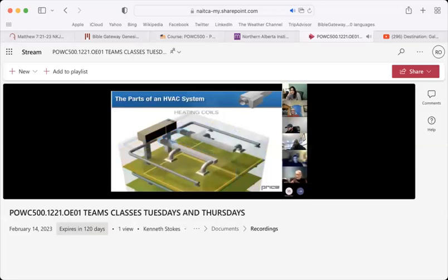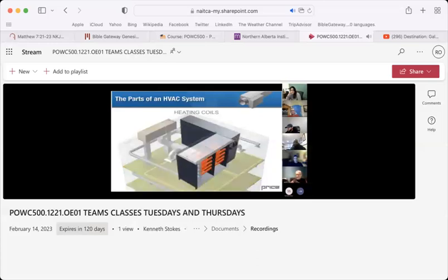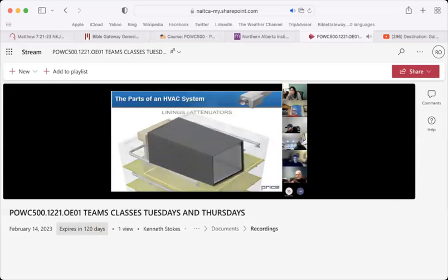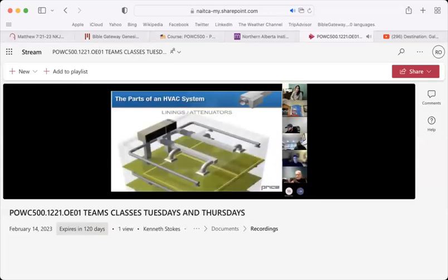Heating coils may be installed after a terminal unit to provide heat on a zone-by-zone basis. As mentioned previously, buildings with a high number of occupants may not require extensive heating even during the coldest months of the year. Heating coils offer an efficient way of providing heat for those few areas that require it and are controlled by the same thermostat system as the terminal unit. Various types of linings are available to dampen noise within a duct. A short length of lined ductwork called an attenuator is often installed following the terminal unit to dampen discharge noise.